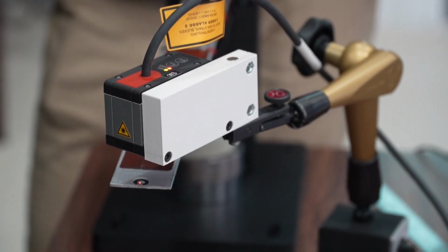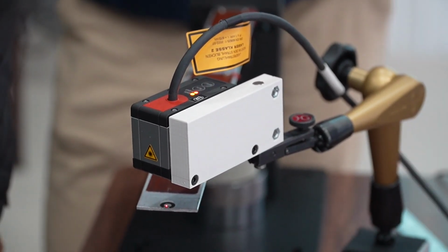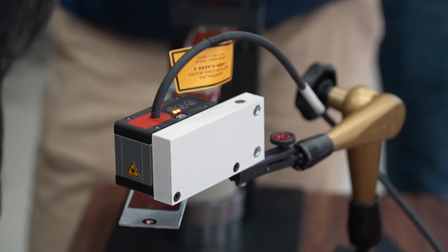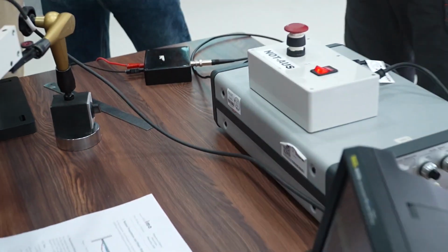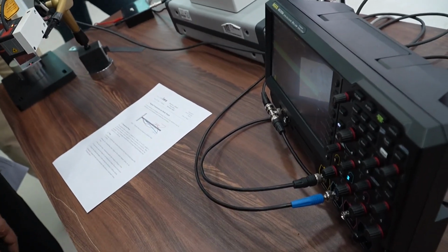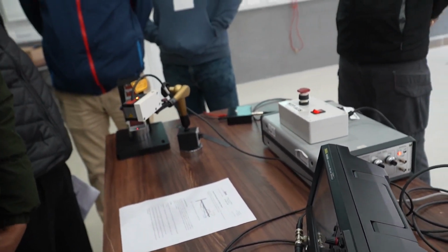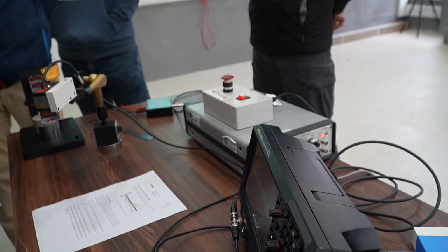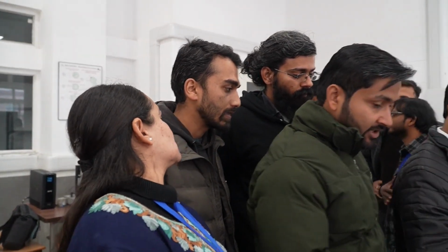Okay, so this is the first eigenfrequency, and now your job is to get the second eigenfrequency. What you do is you now increase the frequency, and see, it will stop vibrating, and then it needs to start vibrating again. At the point where it starts, we can go to acquire, and go back to roll. You see that? A small hint from my side: push G1, and now you can increase. But it will be somewhere above 40 hertz. So you will take a very long time to find it if you do not start with somewhere like 40 hertz. You could also just roll it.